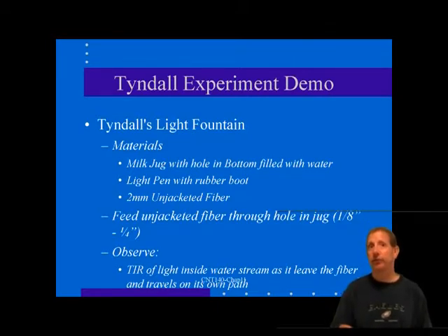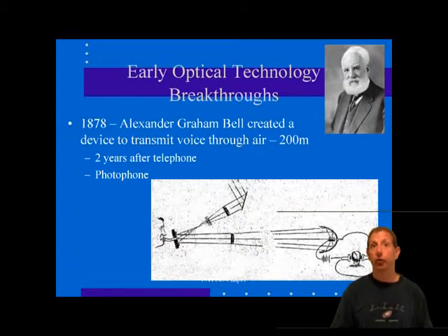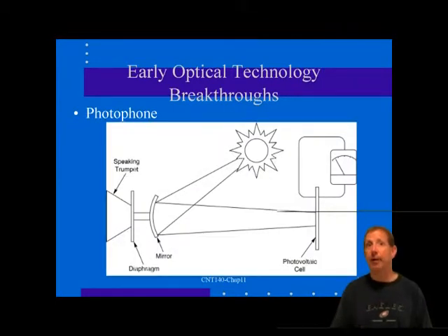The entire portion of circuitry that converts the electrical signal to light is called simply the transmitter, and it includes the light source. Likewise, the circuitry that detects the incident light and converts it back to the electrical signal is called the receiver, and it includes the light detector. In many fiber applications, the transmitters and receivers are pre-packaged devices that are simply mounted on the circuit board of the optical equipment.